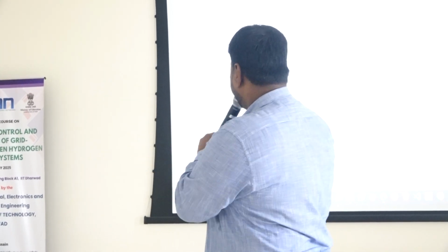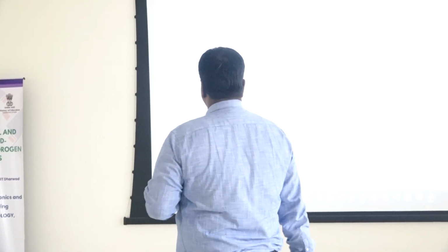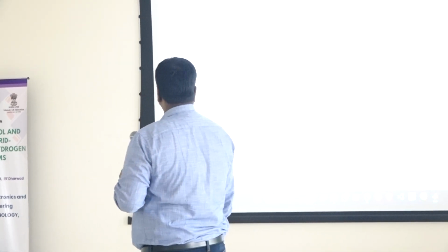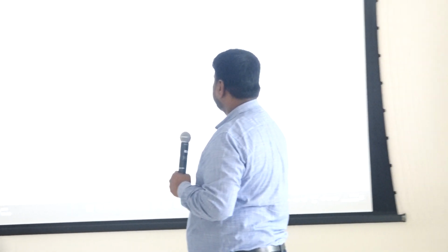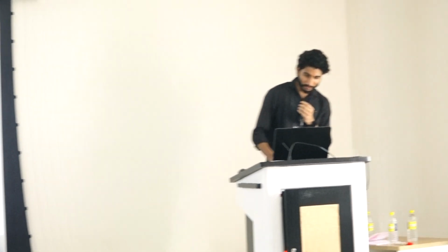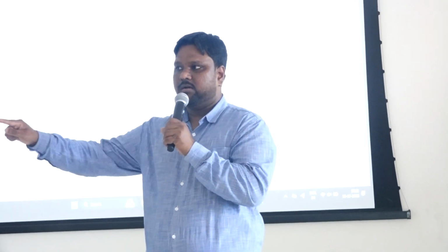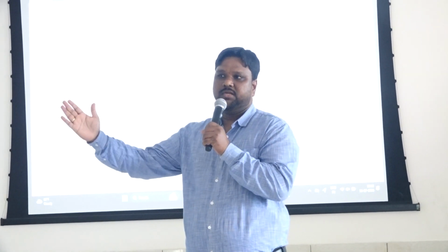Can you give that? Search for pulse generator and double click on it. Now give it the time period as TS, which you mentioned in the .m file, equal to 1 by Fs. That TS, as I told you, is the total pulse period if I consider a pulse on and off.